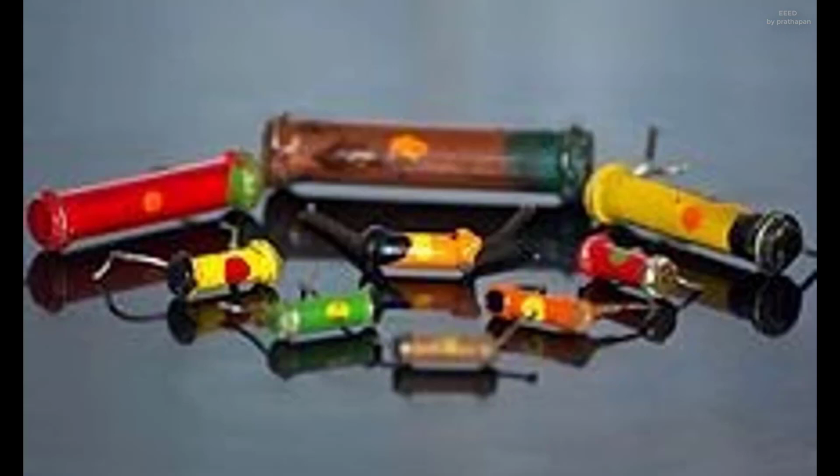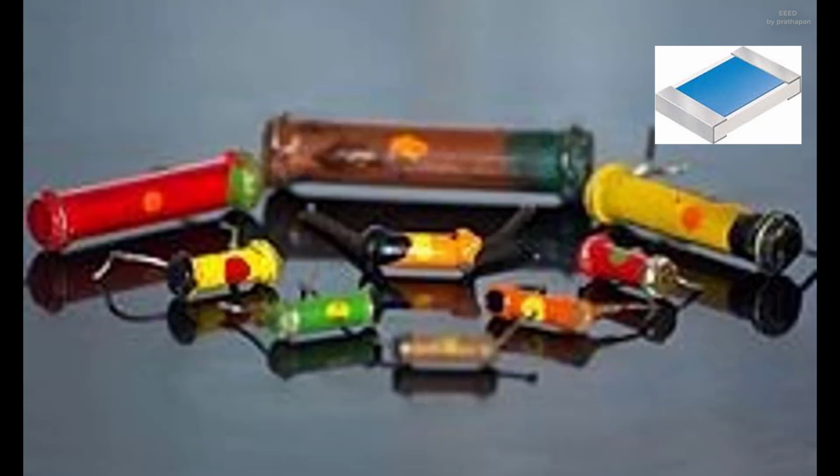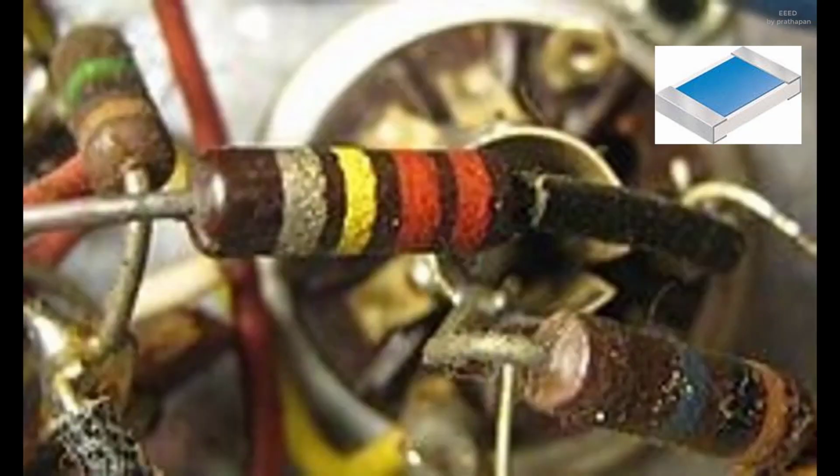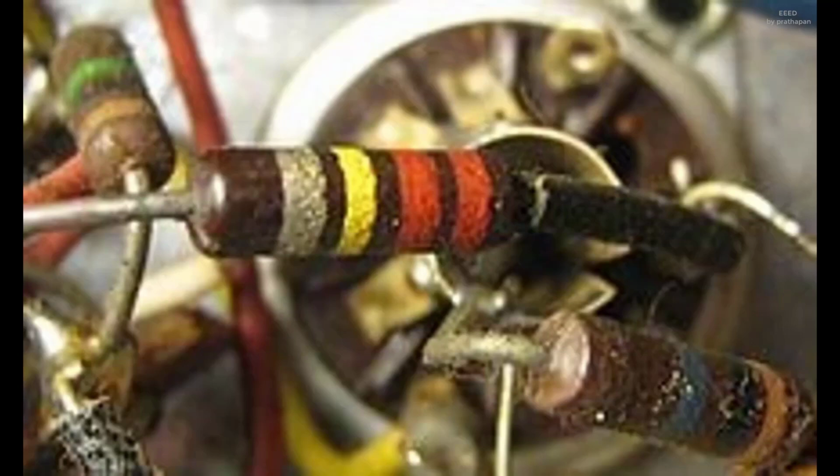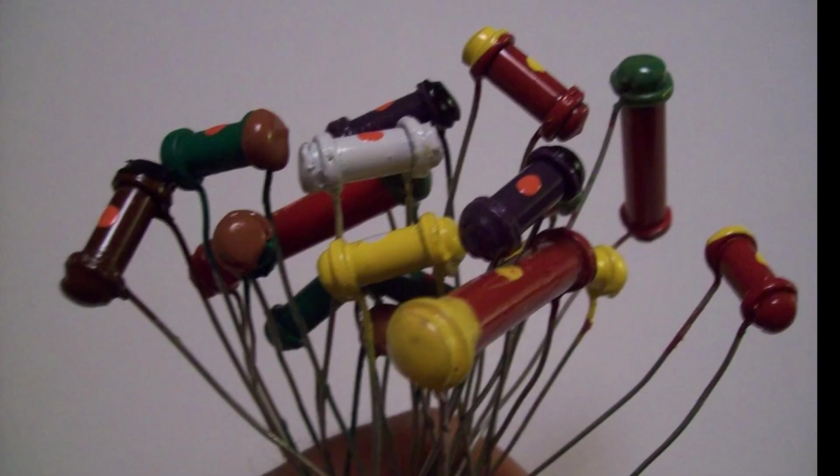Other components may be SMT, surface mount technology, while high-power resistors may have one of their leads designed into the heatsink. Carbon composition. Old-style dog bone resistors. 3 carbon composition resistors in a 1960s valve, vacuum tube, radio. Carbon composition resistors, CCR, consist of a solid cylindrical resistive element with embedded wire leads or metal end caps to which the lead wires are attached.